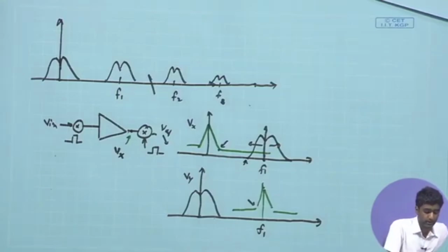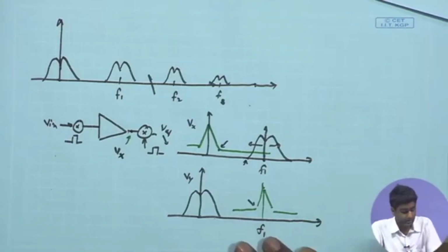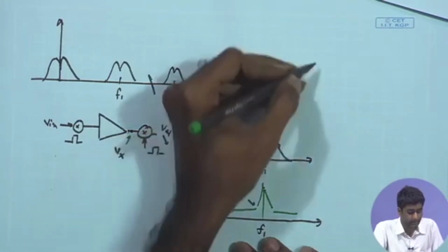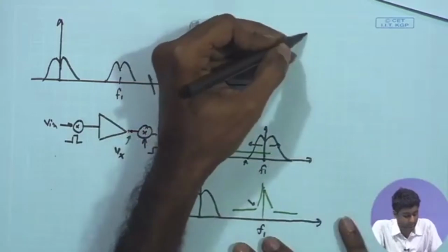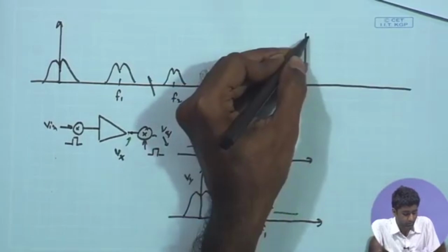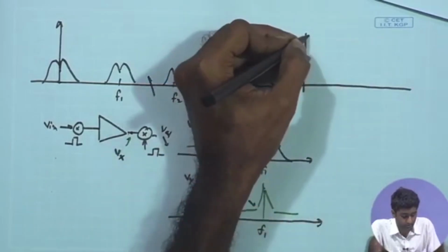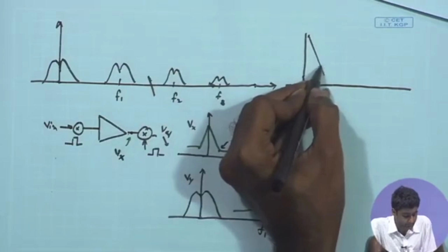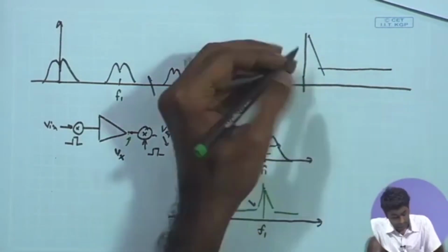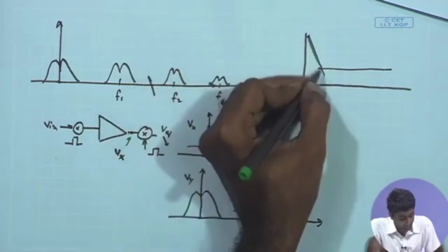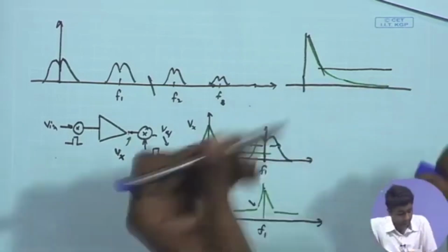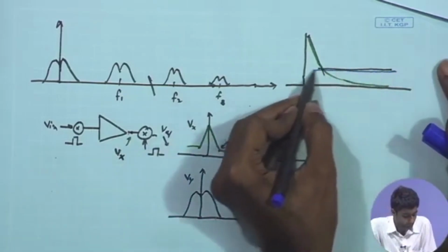Also, ideally, since this is a 1/f noise curve, here we are depicting it with very sharp characteristics, a sharp transition between the 1/f curve and the white curve. We are depicting it something like this, but in the actual scenario, of course, the 1/f curve is going to have a smooth decay, and then you have the white noise which is flat overall.